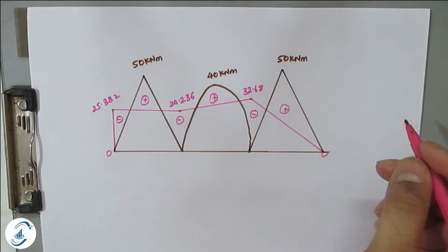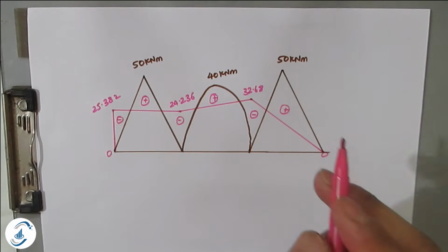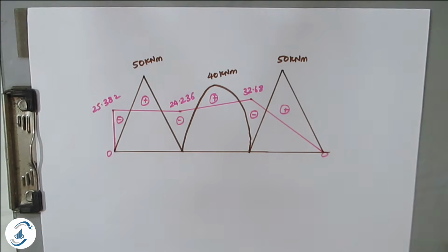So this is how you have to analyze a continuous beam by Kani's method when the end support is not fixed. I have shown you how to modify the last span. You can either go with this method or the traditional method. In the traditional method, 3 boxes will come, and for all members you have to take stiffness 4 EI by L. I hope you have understood this problem.